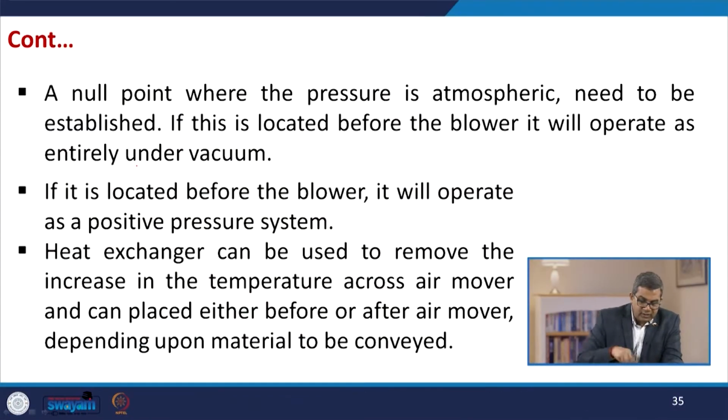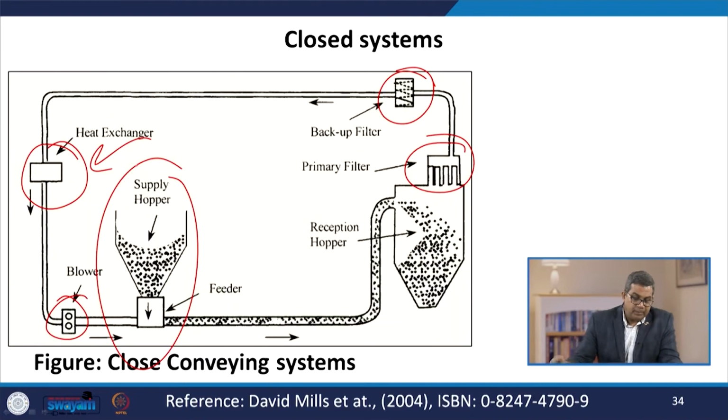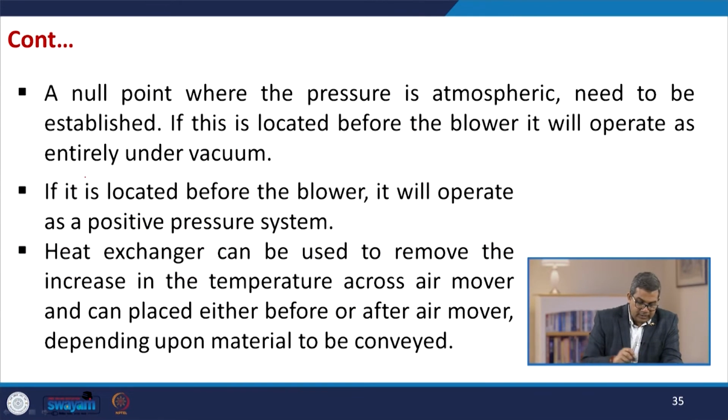Now, a heat exchanger can be used, here you are using the heat exchanger. The heat exchanger can be used to remove the increase in the temperature across the air mover, and it can be placed either before or after the air mover depending upon the material to be conveyed.